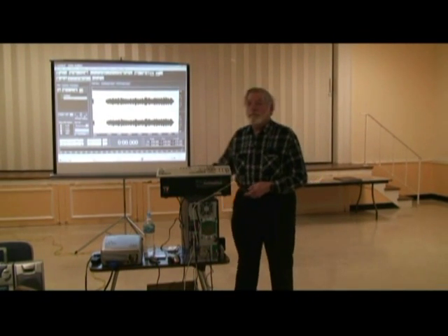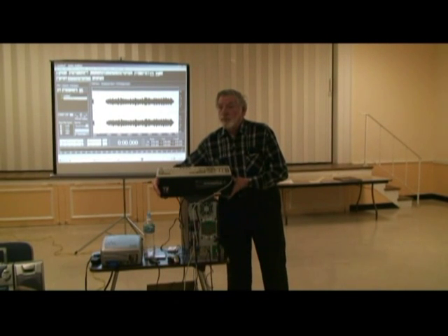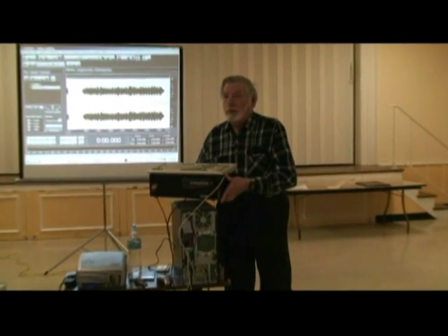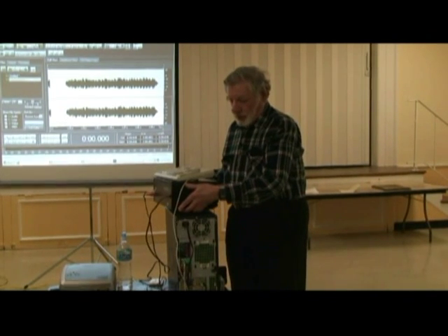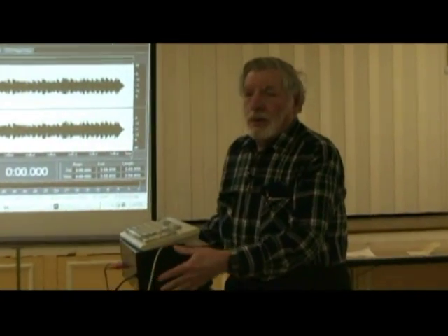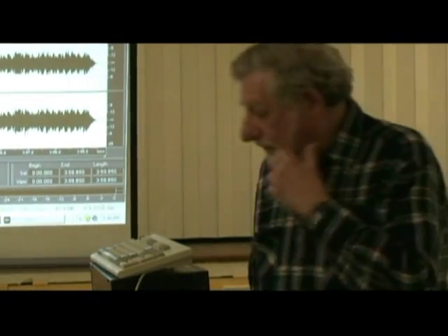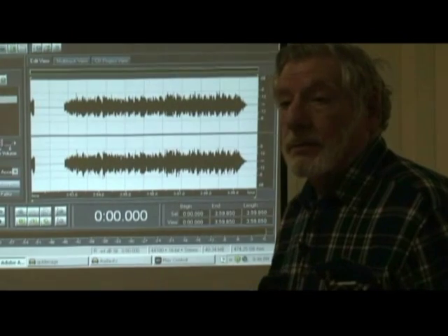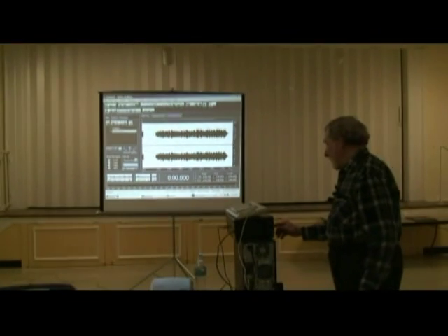Yeah. I think the key to this, though, is if you do have a single output and you put it on a computer, it's going to come across as only one channel. Right, it's never going to divide it. And that's what you found. If you go mono to mono on a computer, you're going to get just the left side or just the right side. It's very hard to split that single signal.